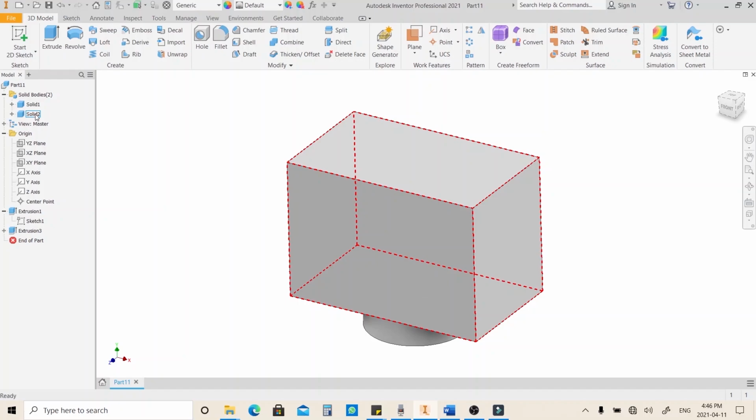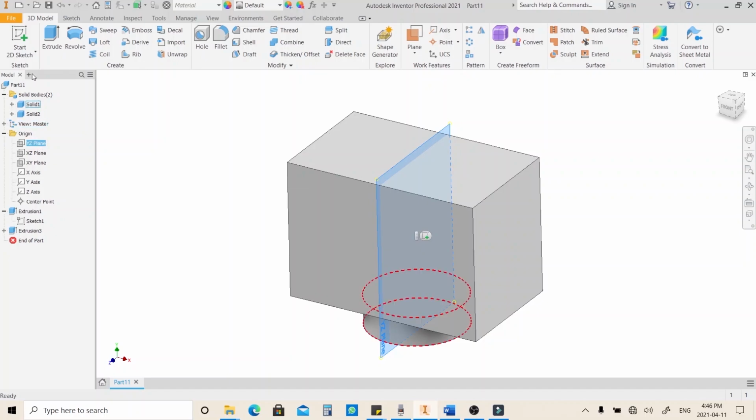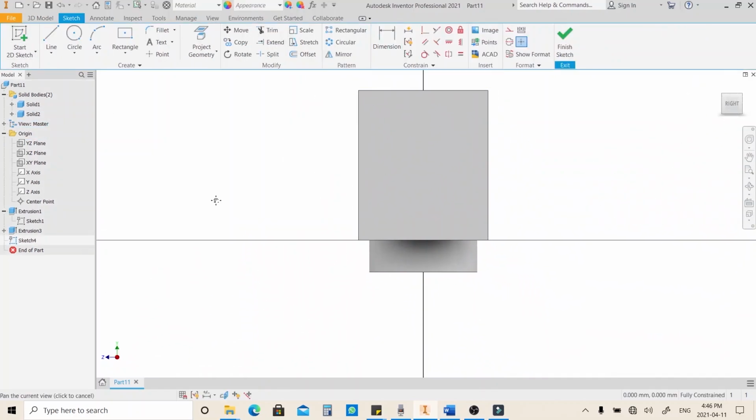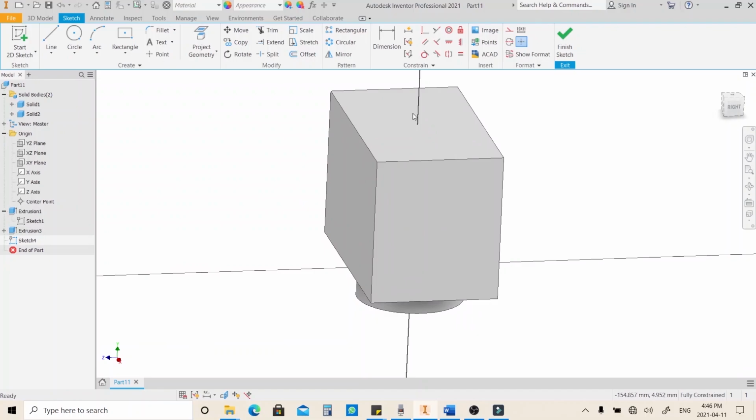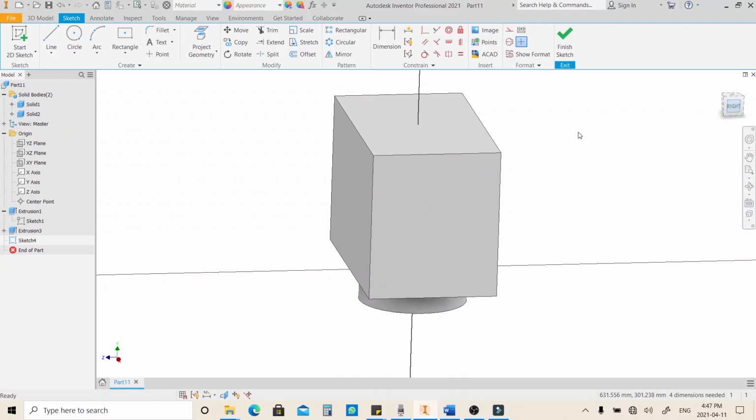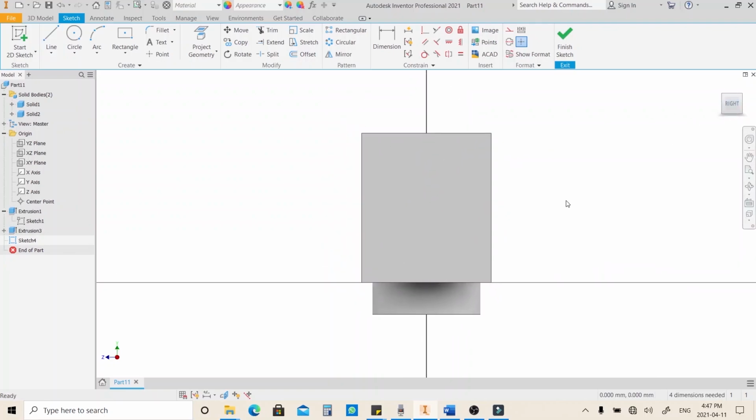Go ahead with another option of extrude. From here, let's try to combine the previous options into one feature. Let's say we're going to make a cut around here. So make a sketch on the YZ plane. Click new 2D sketch. As you can see, the sketch is hiding inside the body. If you make a line here, for example, the line cannot be seen from here.